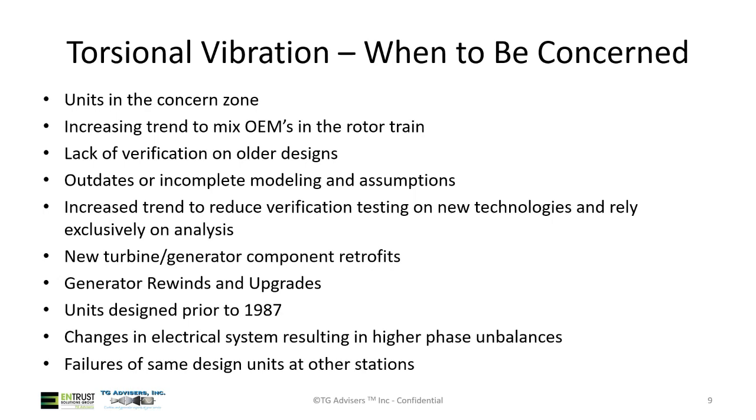Torsional vibration ultimately. So what does this mean for you? You're going through the retrofit or the uprate process. So first of all, you need to understand is your current rotor train, that's your turbine rotor, your generator rotor, are they in the concern zone frequency? Do you have something near 120 hertz? If you're far enough away for the ISO standard, then it's not a current concern for you.